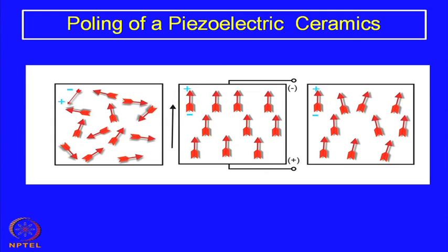normally in a liquid oil, close to the Curie temperature, and then you apply a relatively high voltage for a long enough time, so that you allow sufficient time for the dipoles to align themselves with the direction of the applied field. So, that is the process of poling, which regularly has to be carried out for any kind of piezoelectric materials or piezoelectric ceramics.